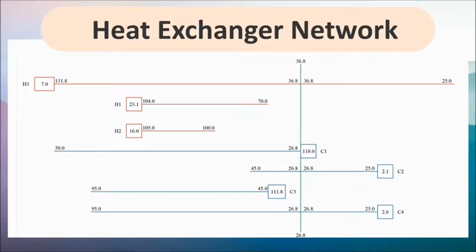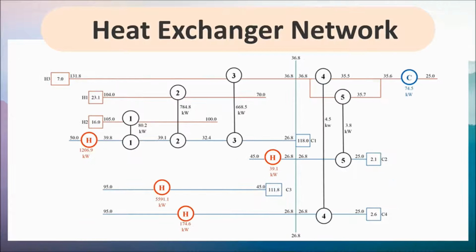Consider the heat exchanger network to design the MER network. First, we calculate the pinch temperature. These are the hot and cold pinch. The values are 36.8 and 26.8 degrees Celsius respectively. Now we show the MER network we designed.